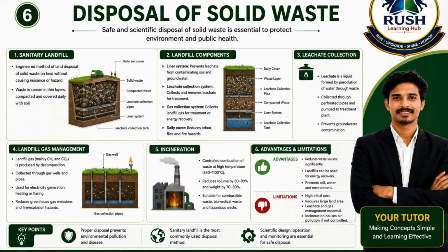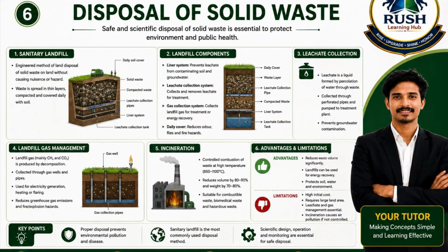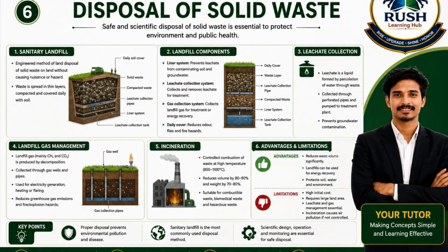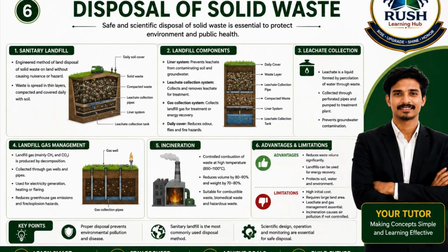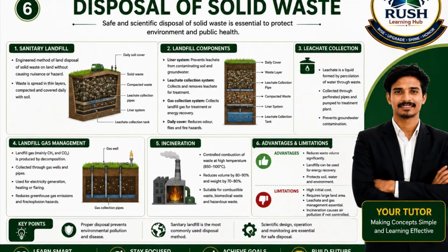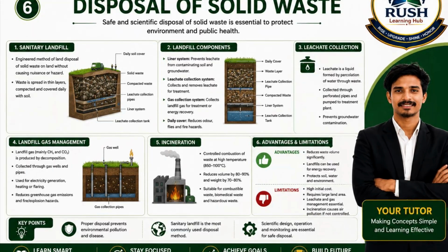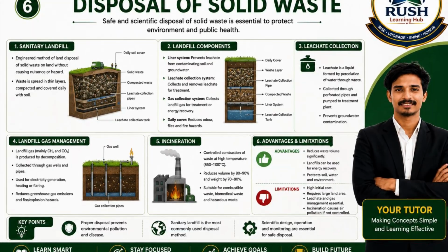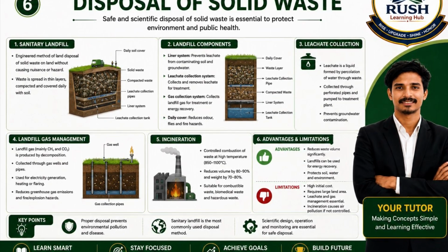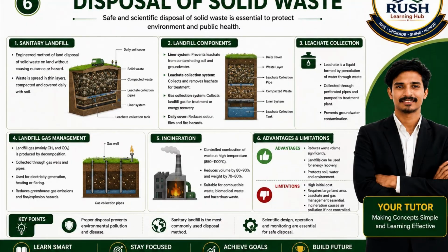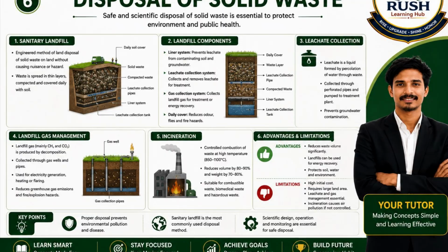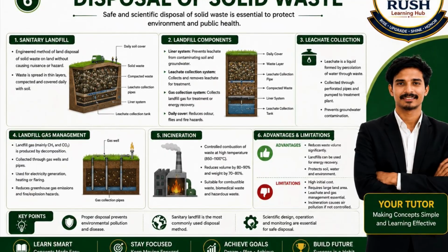Before moving to the next slide, let us quickly revise the important points. A sanitary landfill is an engineered waste disposal facility. Leachate is the contaminated liquid formed when water passes through waste. Methane is the major landfill gas. HDPE liners prevent groundwater contamination. Daily cover controls odor, pests, and litter. Incineration is the controlled combustion of waste at high temperatures. Dioxins and furans are harmful pollutants that may form during improper incineration.